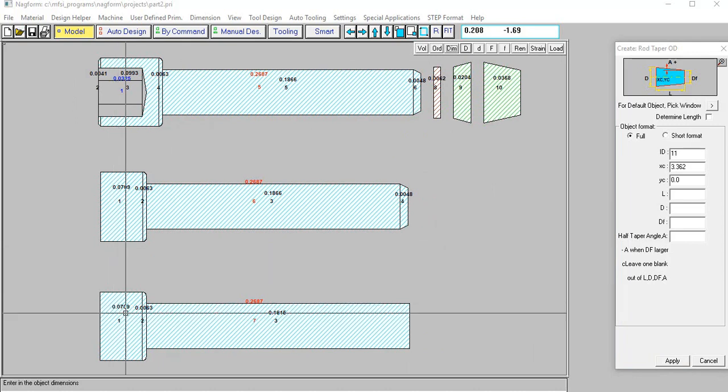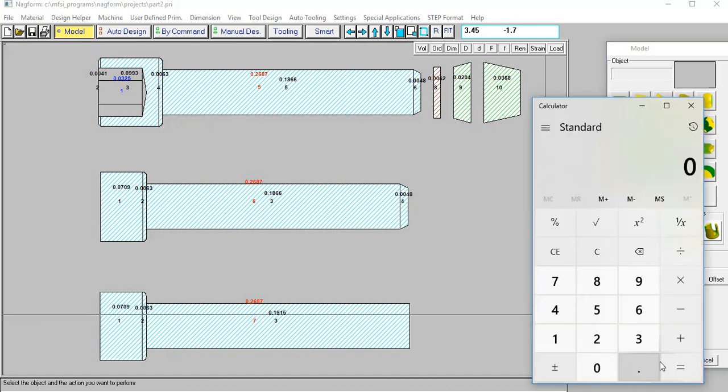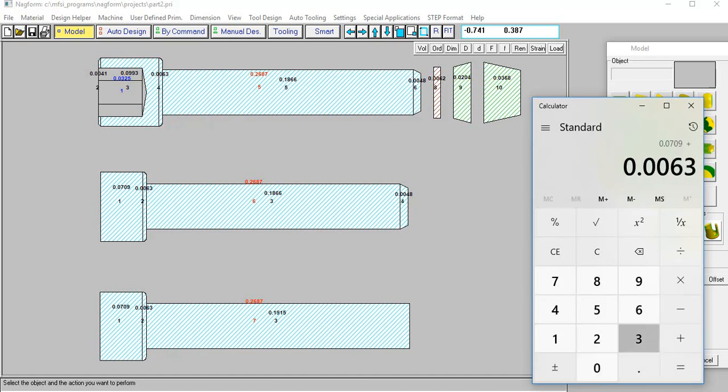So on the left hand side, the diameter is the wire from which we are going to open extrude to the diameter on the right, and also head it. So it's an open extrusion plus heading, one operation together. And that head on the left hand side, we're going to replace it with our double cone design. So we are going to first see what is the volume that we have in the head portion, which is in number 1 and number 2 of 7 on our left hand side. And we are looking at what is the volume we have in these three primitives that we have put together.